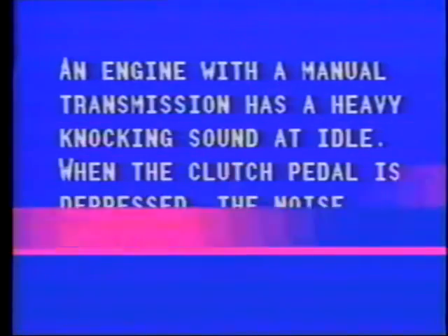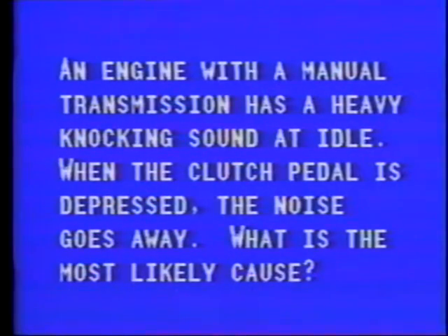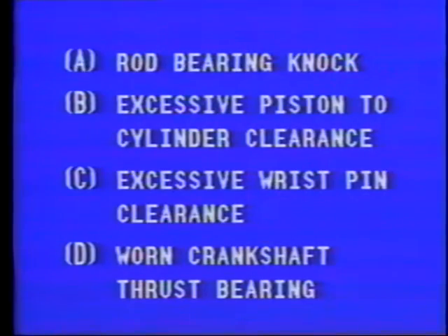An engine with a manual transmission has a heavy knocking sound at idle. When the clutch pedal is depressed, the noise goes away. What's the most likely cause? A, rod bearing knock. B, excessive piston to cylinder clearance. C, excessive wrist pin clearance. D, worn crankshaft thrust bearing.